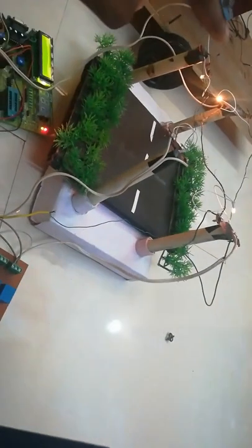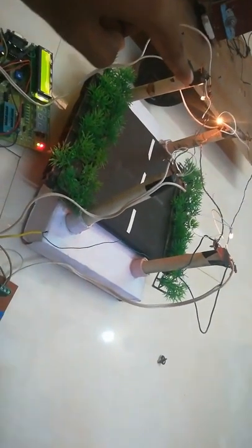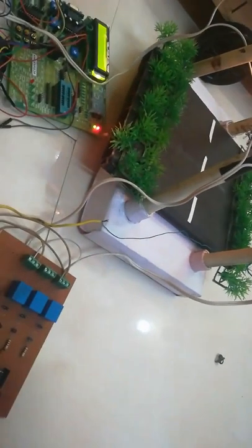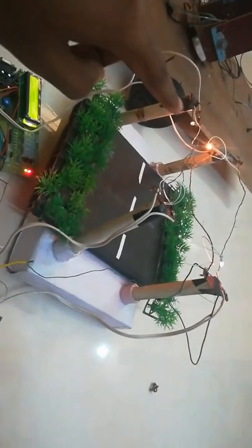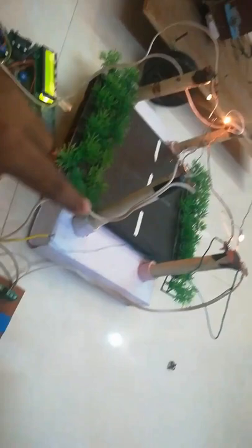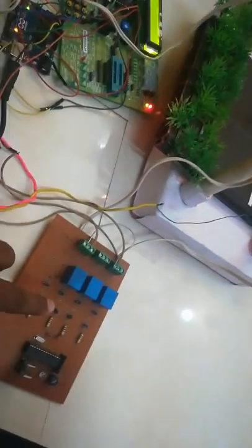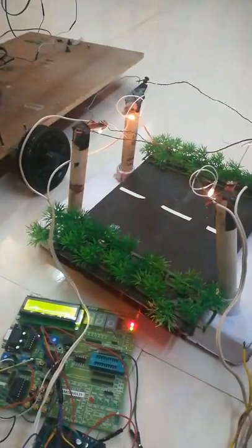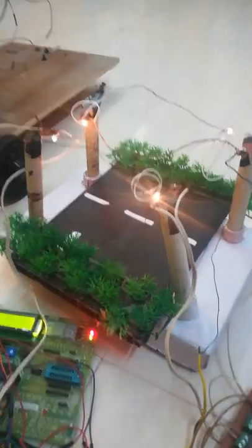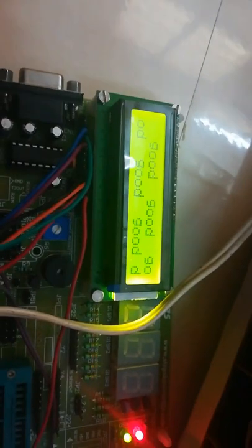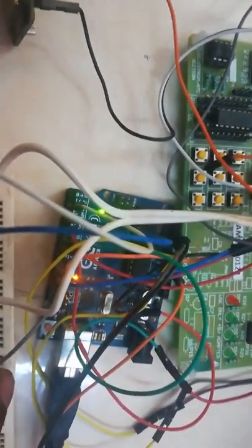Whenever the voltage is coming from the distribution network, this relay will be activated. Whenever no voltage is received from the dead end point, the relay will be turned off. So now all are working properly. Street 1 is working properly, street 2 is working properly. So the display shows good. When I press the reset, how will it start?